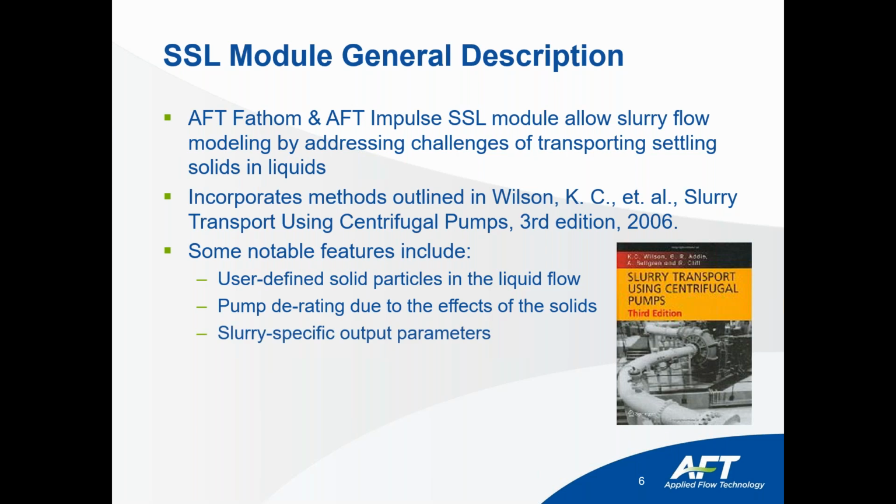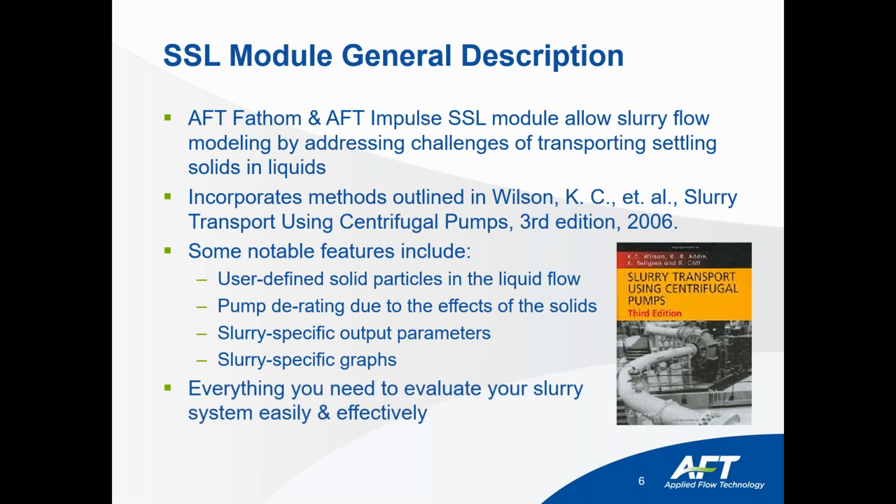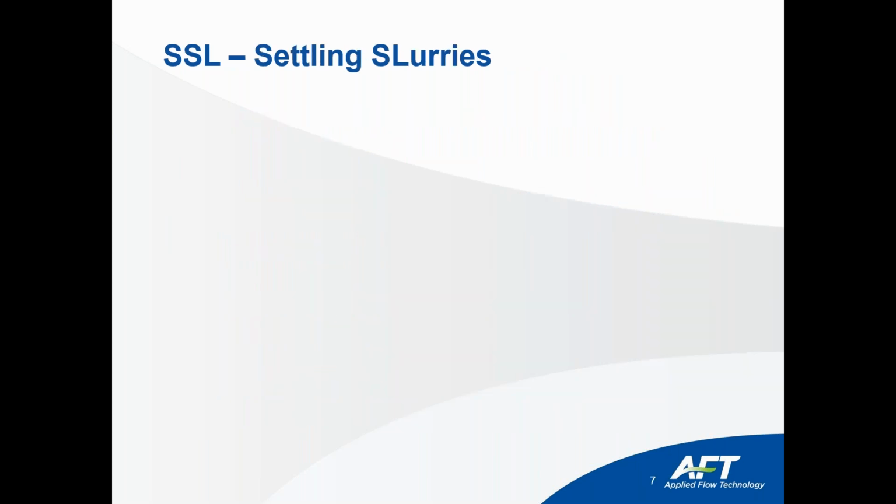You can generate slurry specific output parameters like your Im and Jm head gradients, slurry specific graphs like a slurry system curve, and basically everything that you need to evaluate your slurry system effectively is what can be done with the SSL modules.